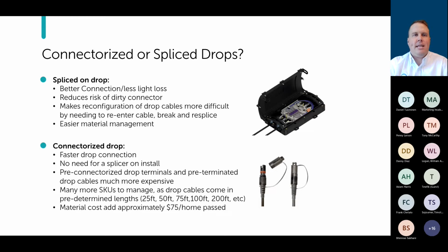However, I will say that sometimes that argument can get overused: oh, you don't need splicers. You go this route, you don't need splicers. You're still going to have splicers in your network. So the argument that you can get rid of splicers is definitely not the case here. And the thing is, splicing technology and splicers have gotten so advanced and so easy to use that going and splicing on a flat drop cable is not nearly as timely or costly as it was even, call it, 10, 15 years ago.